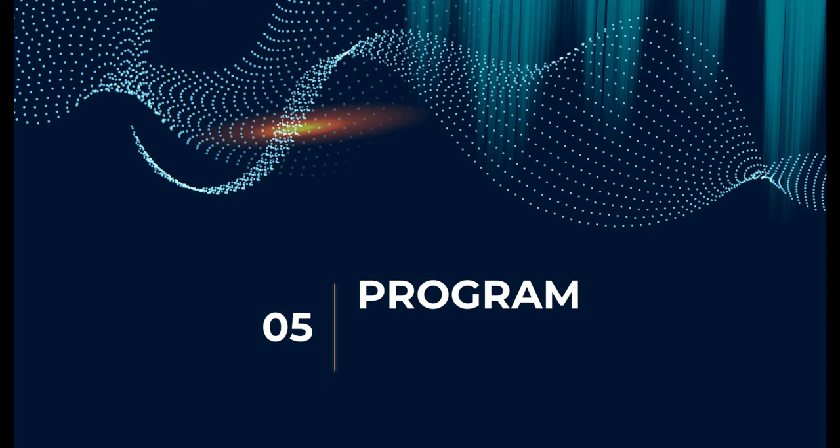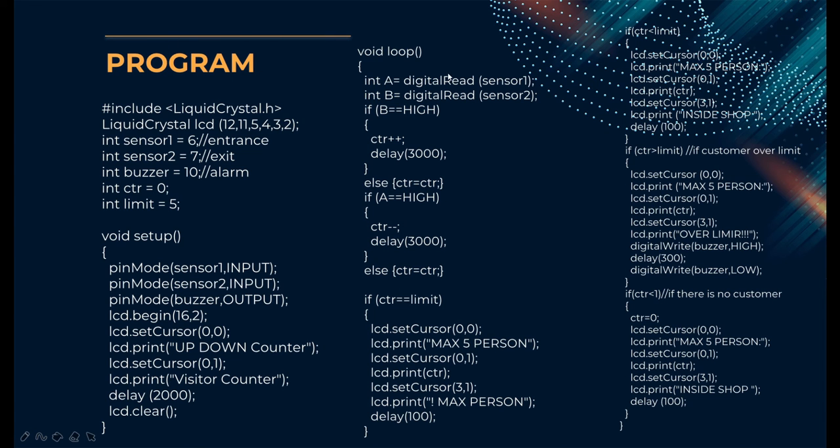Now we will look into the program. This is our coding for our project, and here we have included our LiquidCrystal LCD library, and our LCD pins have been declared at ports 12, 11, 5, 4, 3 and 2. Sensor 1, which is at the entrance, is 6, sensor 2, which is at the exit, is 7, and the buzzer as the alarm is at 10. All these ports are digital, and we have set the limit for the entrance, which is 5.